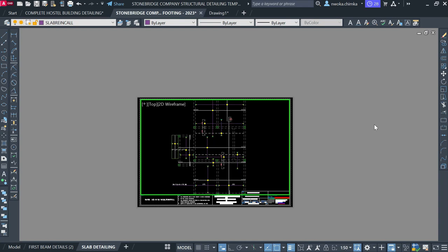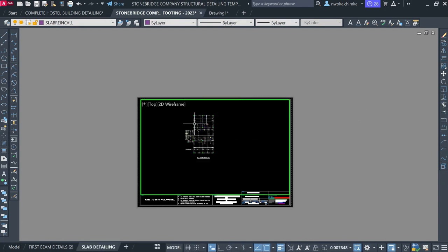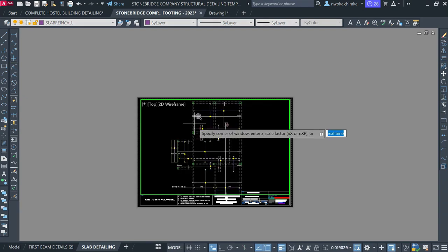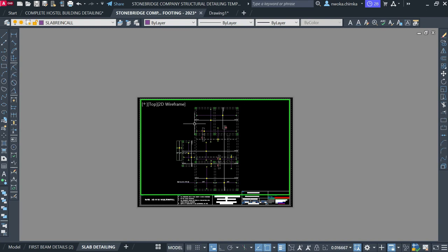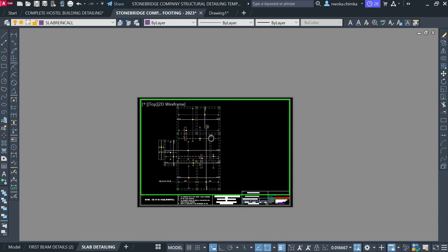Okay, no, this looks too big. So first of all, always click inside this place first to be able to zoom. Once you're able to zoom here, then you can begin to apply your scale. Let's use Z, enter, 1 all over 60 SP, enter. Okay, now this looks perfectly okay for this place. Yeah, we'll have to place our section here for the slab.